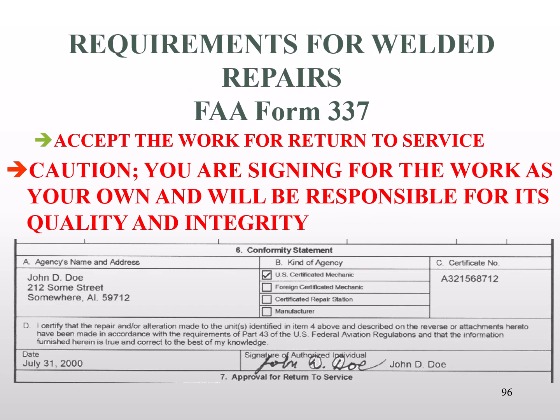This comes up often. What if the repair that we're going to do, the welded repair, falls under the category of major repair? When we add the word major in front of repair or alteration, that means that an FAA Form 337 must be completed. Now, who's responsible to complete that form? The mechanic doing the job. Who has the authority to approve for return to service the work done on that form? Well, you must be a certificated mechanic with an inspection authorization.